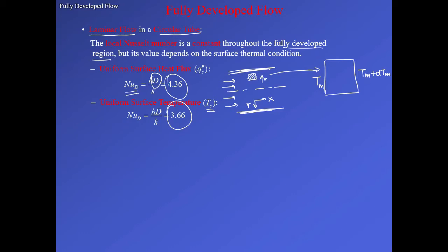When the pipe surface imparts energy, that flows in the radial direction as conduction. So you have the heat conducting in the r direction, because there is no convection in the r direction, because the flow is happening in the x direction. So this Qr, which is the conduction in the r direction, is the heat entering because of conduction, and then the heat leaves; since the volume is infinitesimal, we call this Q at r plus dr.